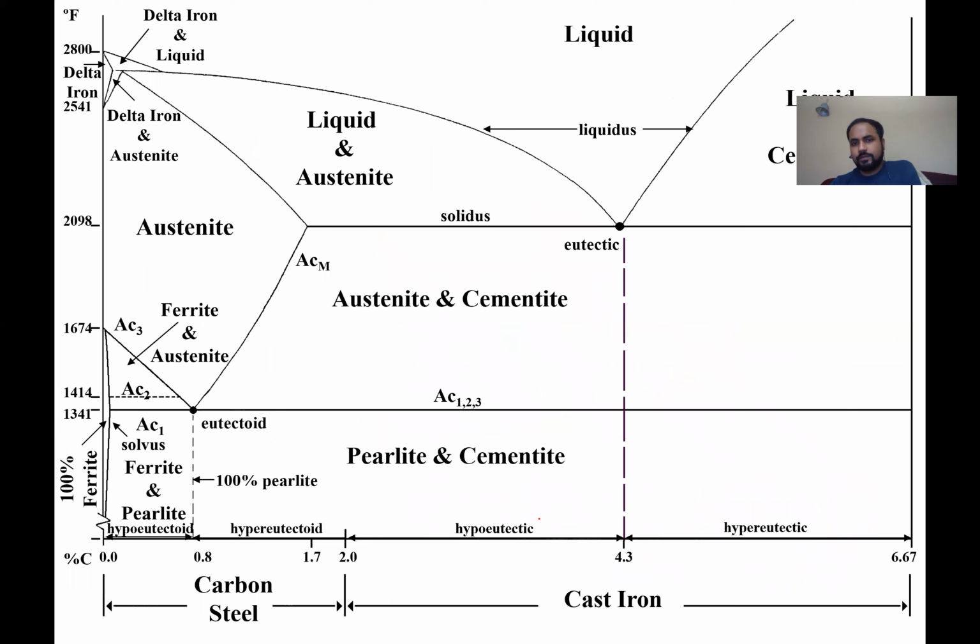Now, one question you guys might have here, or if you know it, that's even better, is about a phase which I was talking about: martensite. But that martensite phase is not visible anywhere in my iron carbon phase diagram. That's because this phase diagram is showing you everything at equilibrium condition. So everything is happening super slowly. If you heat up something and you are cooling it down really slow, then you form perlite. But if you are doing quenching or something fast, that is not visible on your iron carbon phase diagram. Iron carbon phase diagram just shows you the equilibrium phases and equilibrium processes.